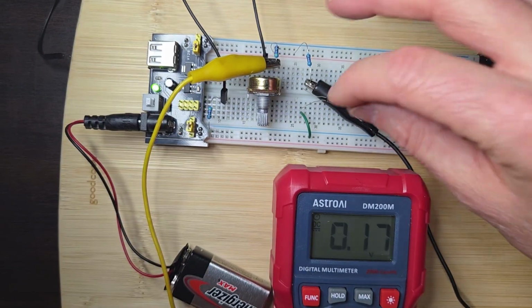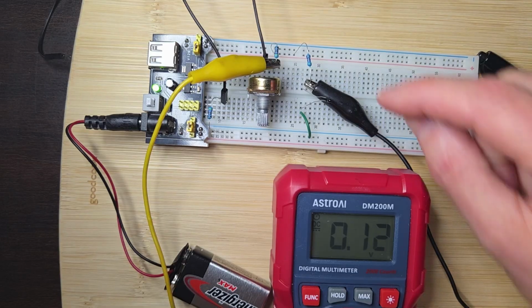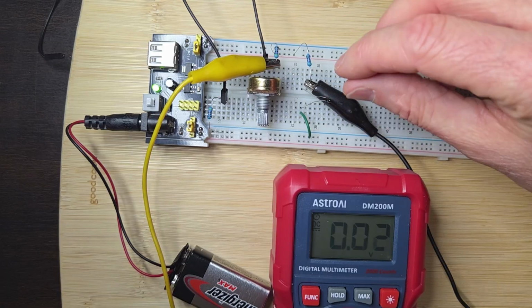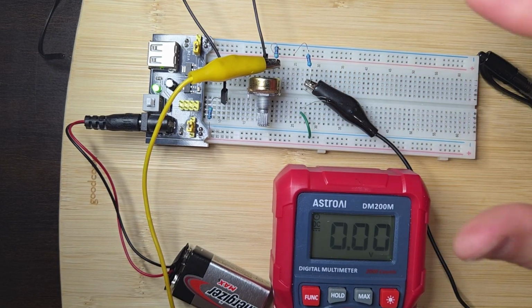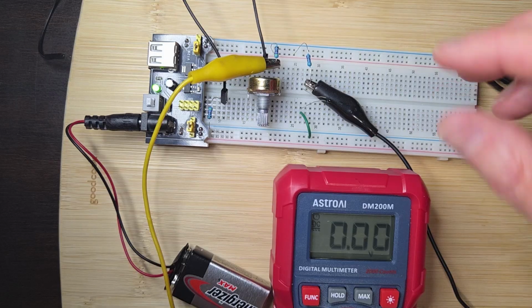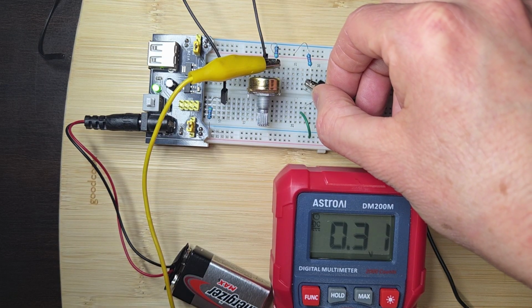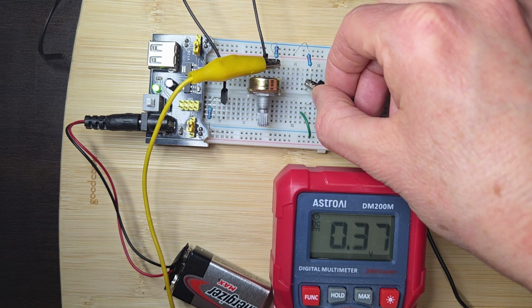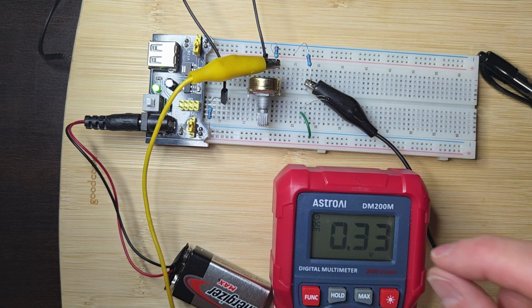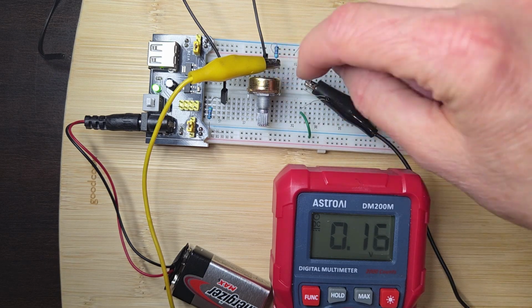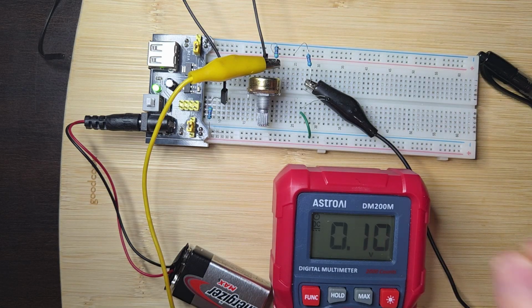So essentially what we've done is we've built a sensor, right? And so I could put a light sensitive resistance in here, where if you turn on the light and it changed the light variable, this low voltage would vary. And what you'll see in real life is this small voltage can be used by an Arduino or a controller to read these little changes in voltage and then tell how hot something is.